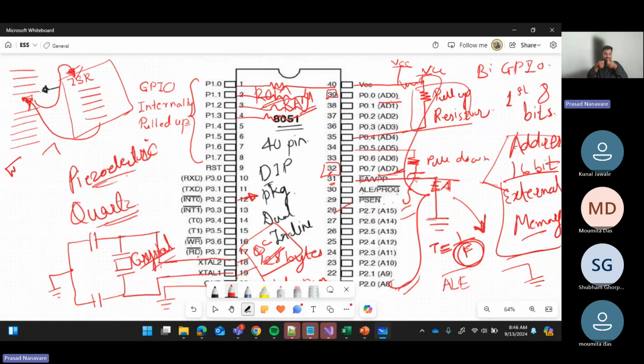So whenever we give electrical signal to a crystal, it generates mechanical vibration, and conversely, we can convert those mechanical vibrations to a constant frequency, and this frequency is fed to these two pins, okay, and these two pins are further connected to an oscillator circuit, and this oscillator is generating this constant clock cycle for our CPU. Understood now? Our 8-bit CPU.